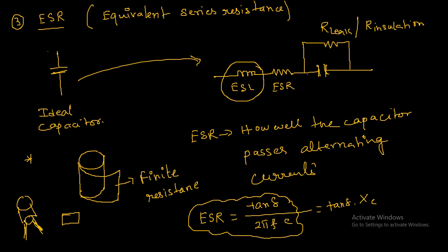If you have a very precise, high speed design and you don't want ESL to affect your design parameters, then ESL creates a problem. You want a very low ESL capacitor, so you can opt for the SMD capacitor. Its ESL is almost half of the leaded type.